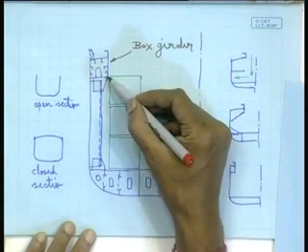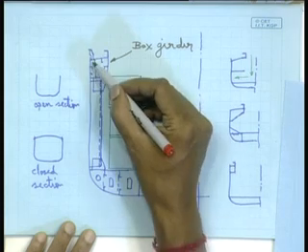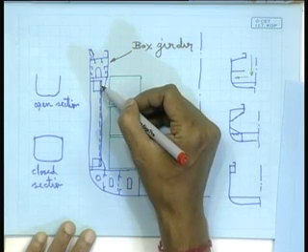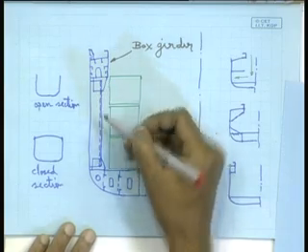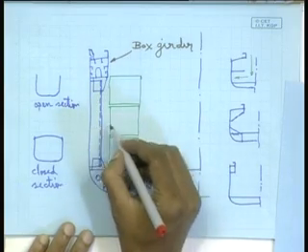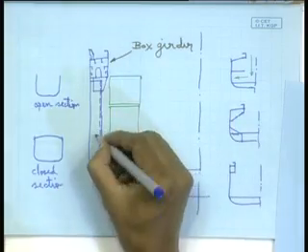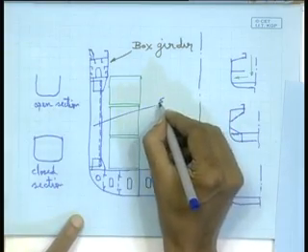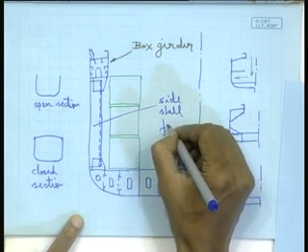So, this bottom plate is stiffened by these brackets, just like these plates are stiffened by these longitudinals. This side shell frame will be there at every frame position, isn't it?